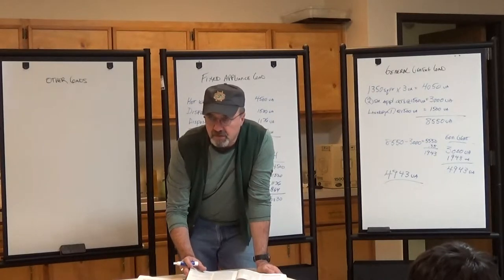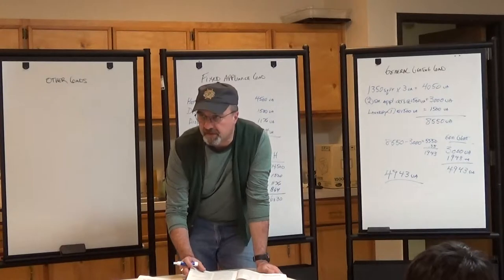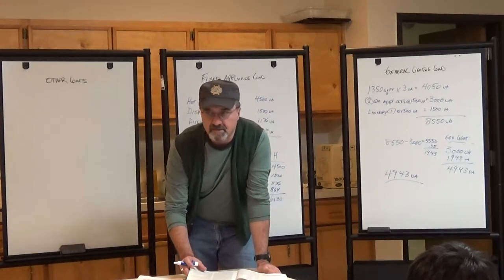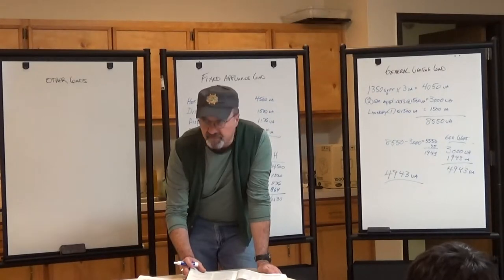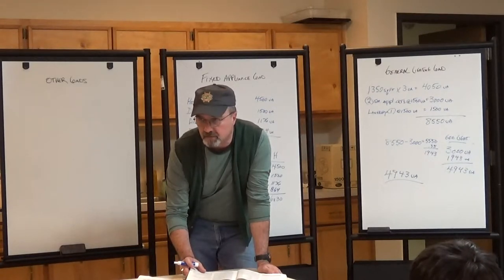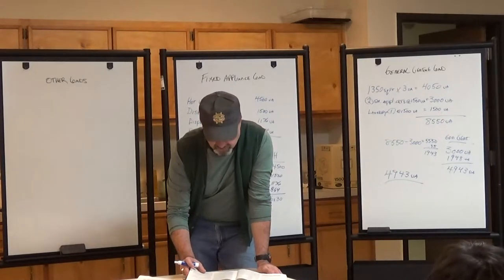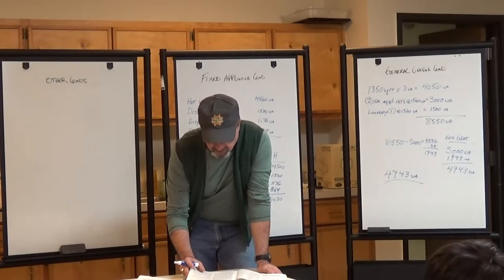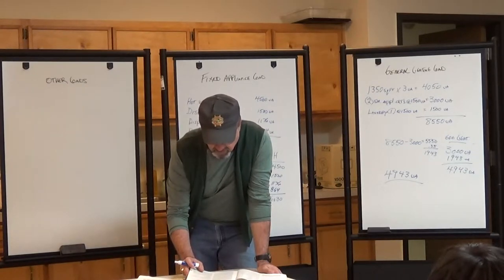Okay, so when we look at the fixed appliances fastened in place, the code allows us a 75% demand factor for 4 or more appliances, but as the article said, it cannot include the dryers, electric ranges, space heating equipment, or air conditioning equipment for a single family or multifamily dwelling.